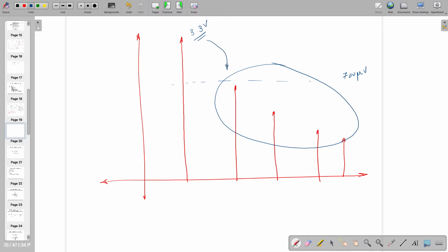The distance between this fundamental and the noise is going to give you the SNR, and this SNR has to be defined from the required dynamic range of your circuit. That is already defined. So from the dynamic range you can find out how much required noise you can have. When you are simulating it, maybe you will see some value of noise. That noise has to be budgeted for a given range. That is how it has to be done, right?